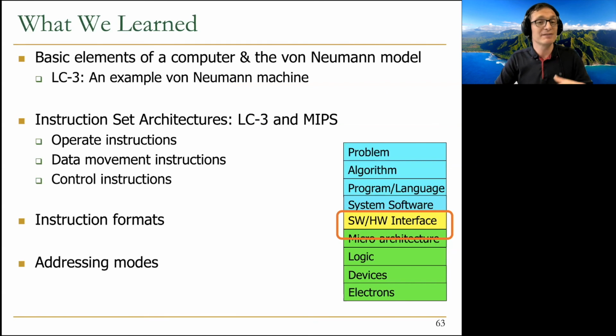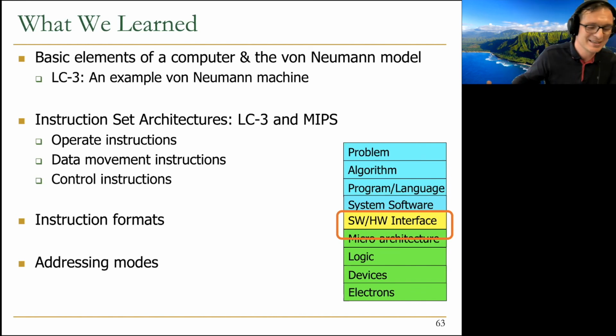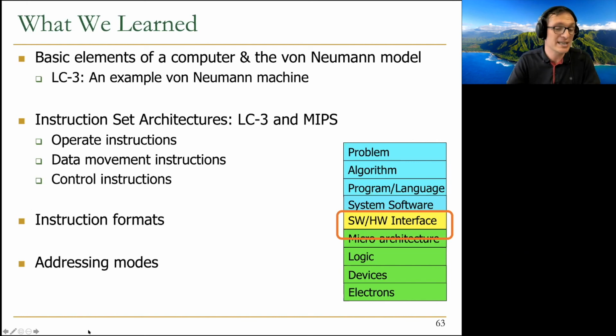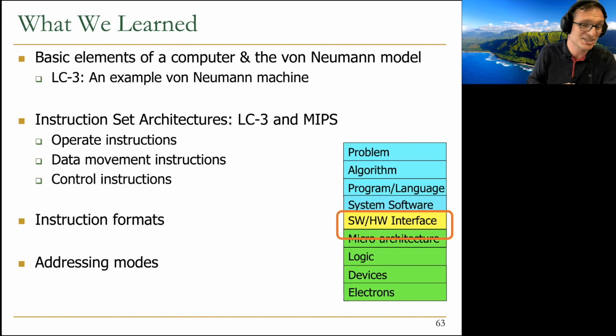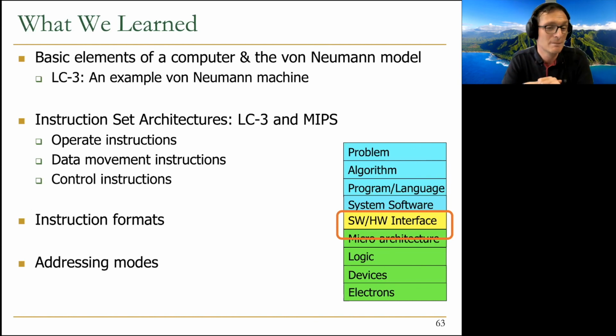But I will also mention what we have not learned, which may actually be useful for some of you, because some of you have more advanced questions, like, for example, why is Apple M1 executing x86 code better than x86? There are multiple possible answers to this, of course, but one of the things they could be doing really well is translating the x86 ISA, instruction set architecture, into their own internal instruction set. That's one technique used to translate one language to another internally very quickly, so that they can potentially execute it much more efficiently. And that is an old trick that was used by other architectures in the past.